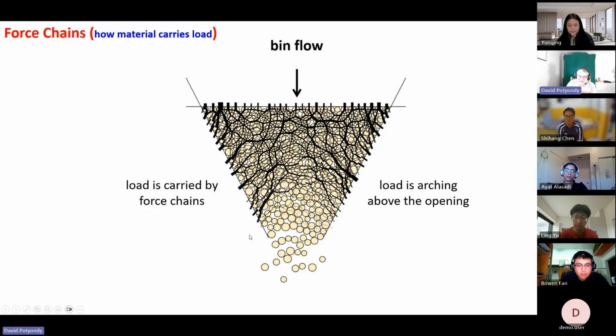They're going to be related to the width of this. They're going to be related to the number of particles across. They're going to be related to the friction coefficient, and they're going to be related to the shape of the particles. Big, weird, elongated strands are going to be more likely to sustain a stable arch than little discs, okay?